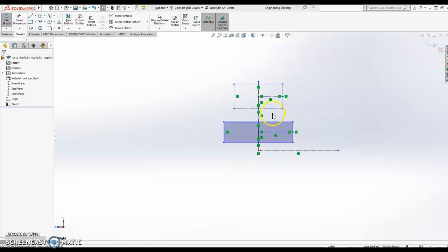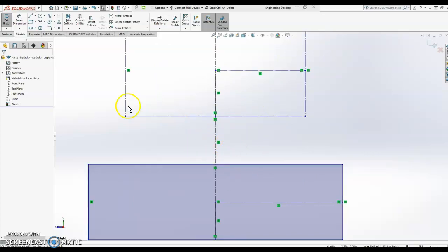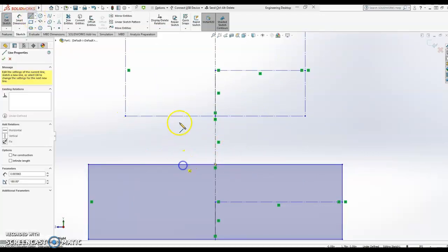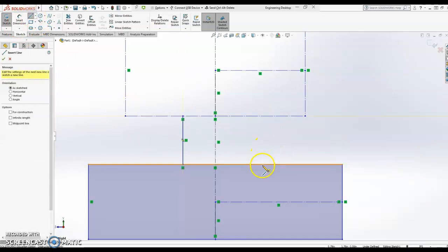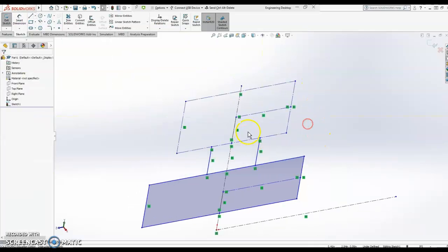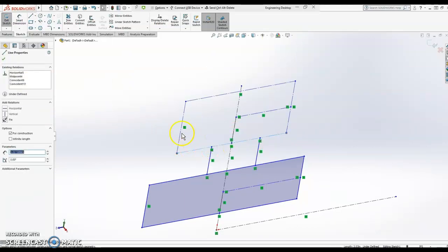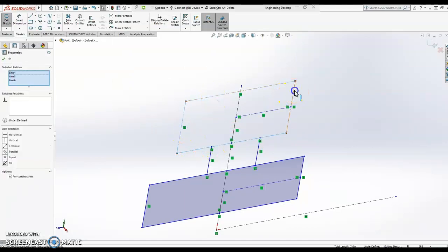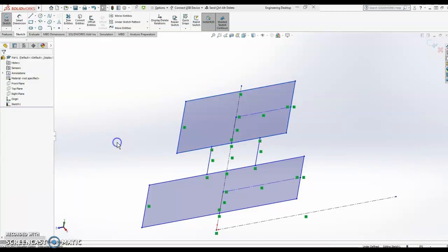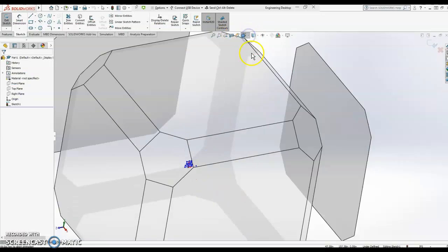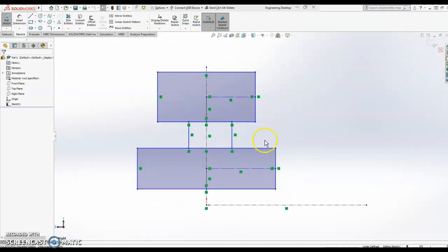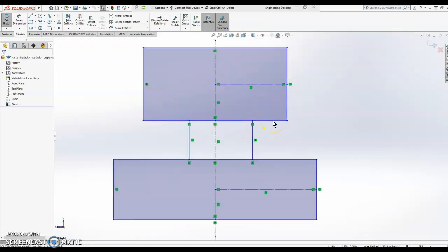let's start creating our shaft here in the middle. So we're just going to drop two lines down, here and here, and then here to here. Of course, I just noticed that I ended up turning all of these lines into construction lines. So we're just going to go back and hit Control, hit my 4 lines, take off construction, turns them back into real lines. And then I am going to look back along that plane. So I go to the view box here and pick the arrow. That looks at right orthogonally.